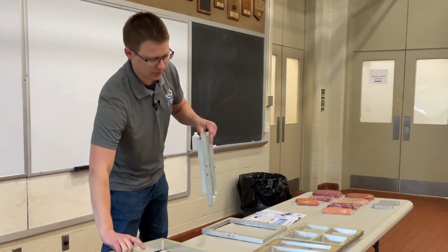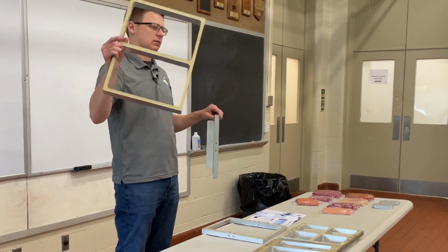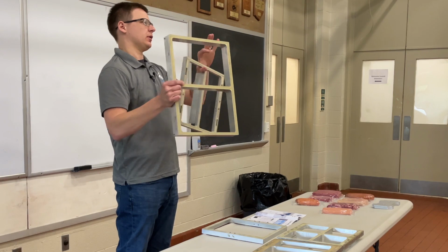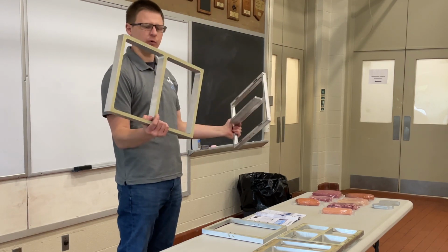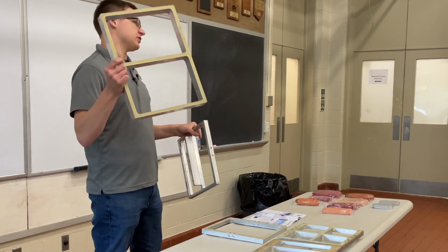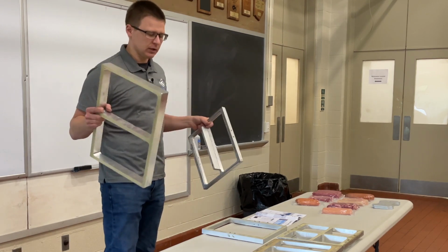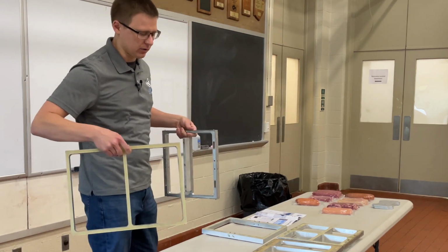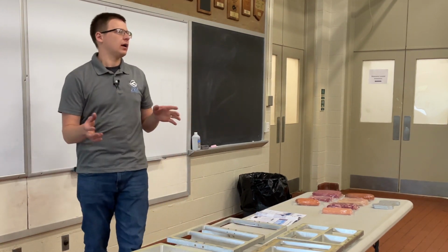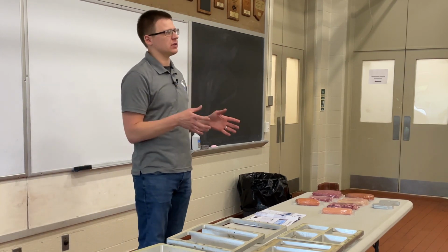So you can obviously see these are very different. The size of this is considerably different. This came off a bigger die. The machine uses a 460 millimeter wide by 300 millimeter long die. This one, or maybe it's more than that, came off a 320 by 300 die. The way you can split this up and configure it is totally different from how you can split this one up and configure it. So start with the right die, figure that out and see what's available to you, and then make sure it's divided up correctly and will fit your product. And that's the biggest thing I can stress: make sure that your products will physically fit the dimensions they're giving you.